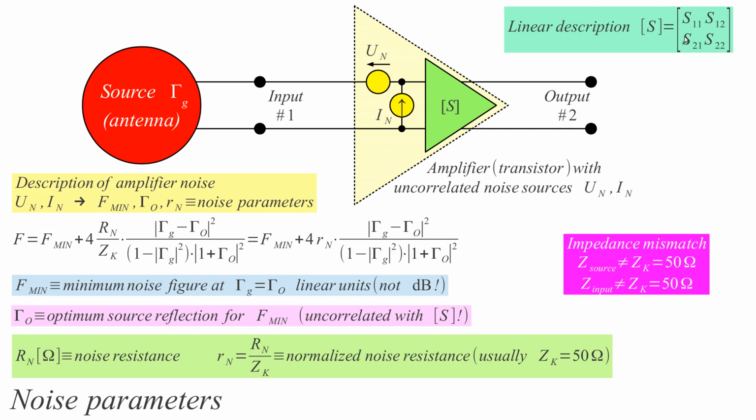Noise parameters may require quite weird impedances here. A low noise amplifier typically has a negative input resistance, so it is actually reflecting more noise out to the antenna than it's receiving from the antenna, because its input reflection coefficient is larger than 1. Such an amplifier is potentially unstable, but we want the lowest noise, and we have to work out to get that lowest noise. This is very difficult to do.